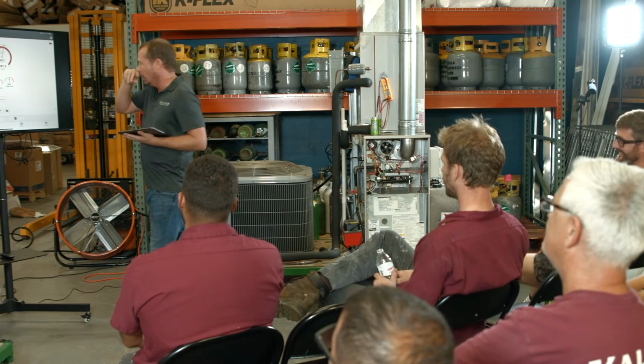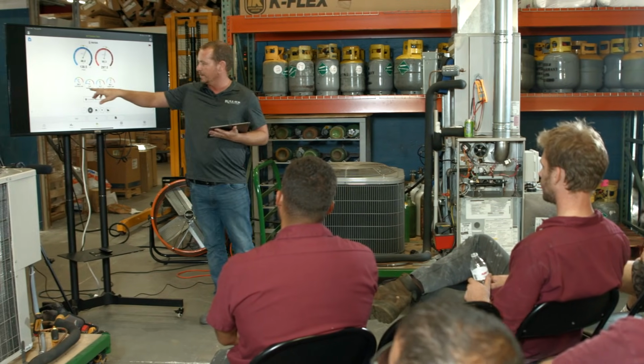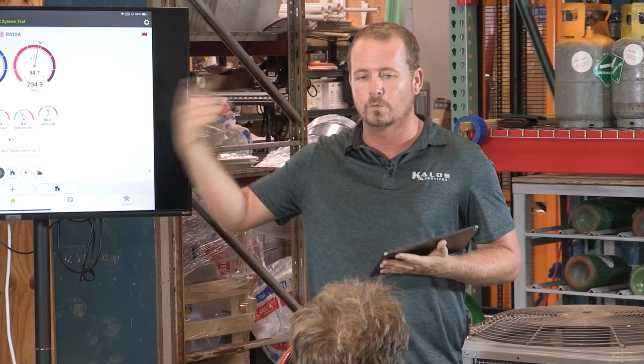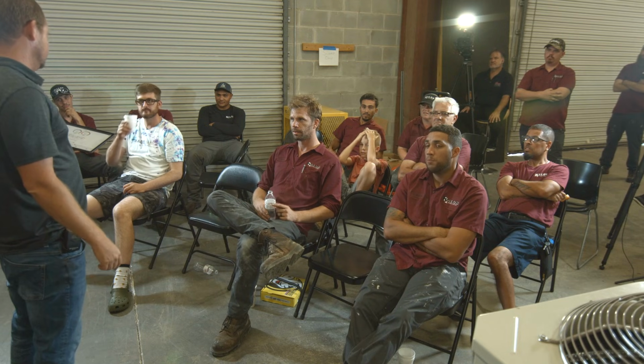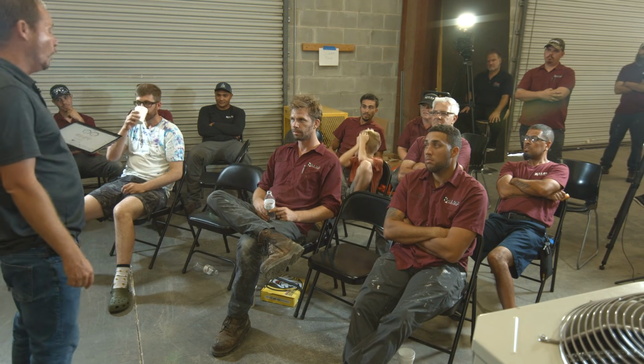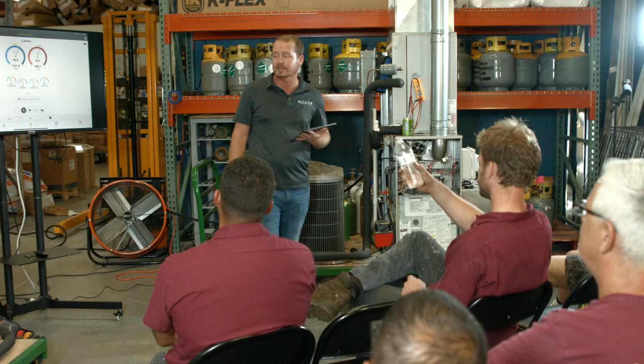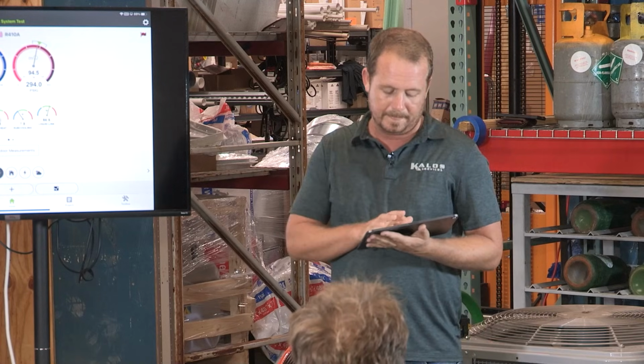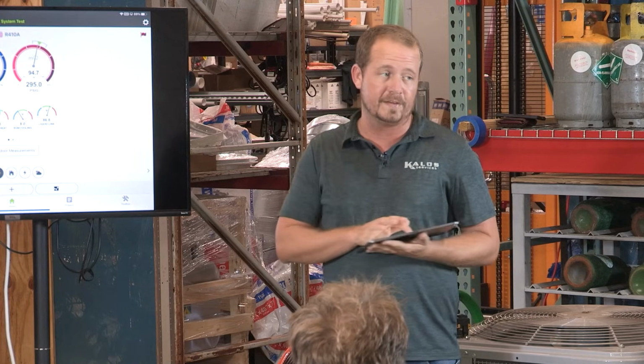So, what do we call what this system is doing right now? There's a term for this. It's hunting, that's the moving around. But low superheat is called what? Flooding. Overfeeding is the term I would use. It's not actually flooding because we don't have zero superheat. True. Zero superheat would be flooding. But we're overfeeding our evaporator coil.